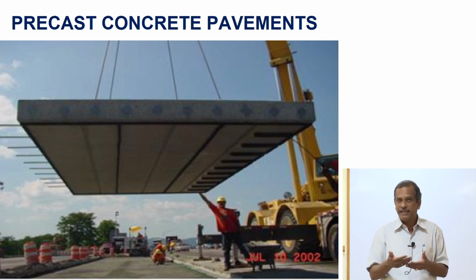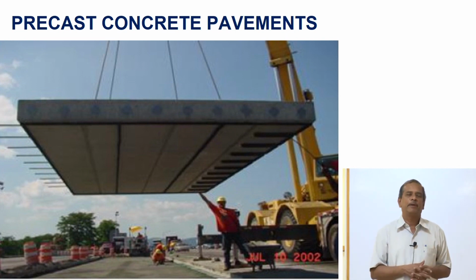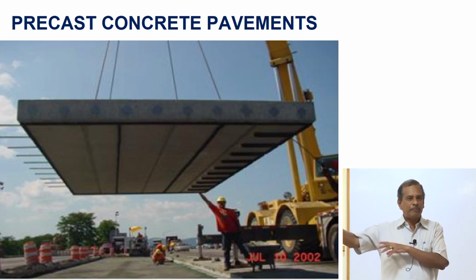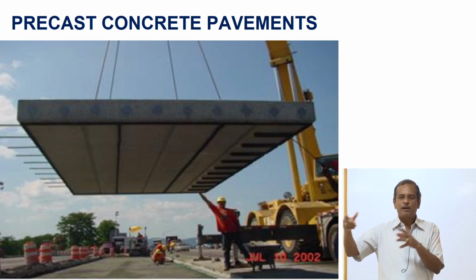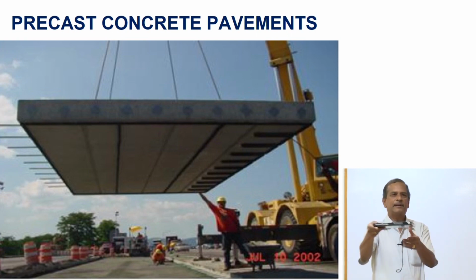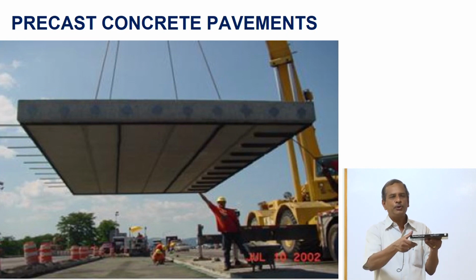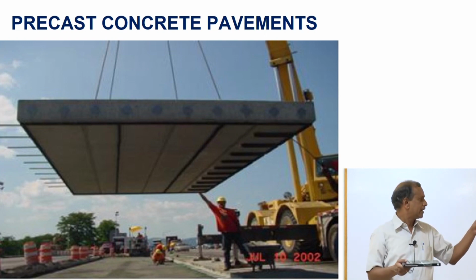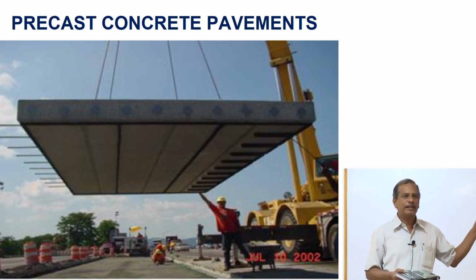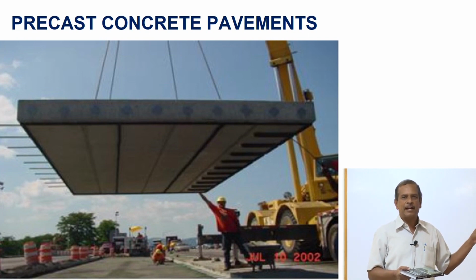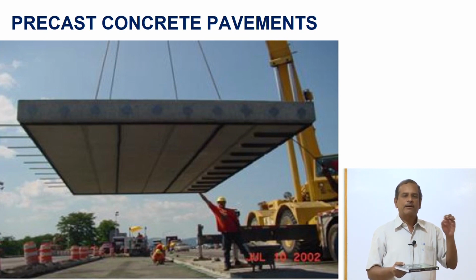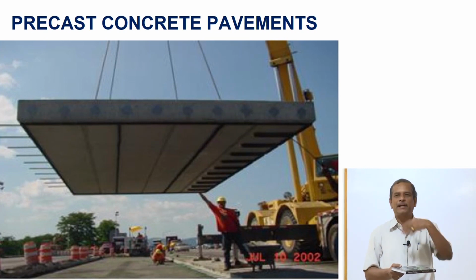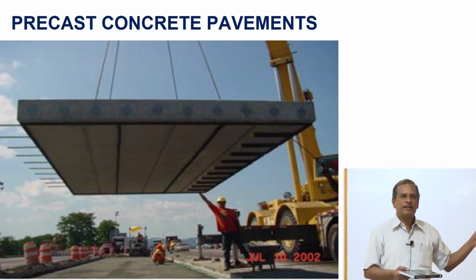Alternatively, it's time that we look at precast concrete pavements. Can I fabricate these concrete pavements elsewhere, bring them to a site? I can fabricate slabs like this, bring them to the site, assemble them, and then open the road to traffic. You can do a post tensioning after you fabricate all these and arrange them in the section. We have started adopting this for the first time in the country for the outer ring road at Nagpur. A research work is in progress at IIT Nagpur today. So, concrete pavements, I think it's time that some of you can become an entrepreneur, can have a company for precast concrete pavement.